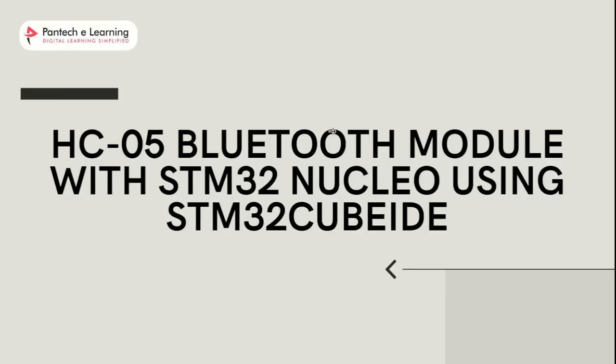So we will use an Android application to communicate with the STM32 Nucleo through this HC-05 Bluetooth module. And also we will see an example of controlling an LED from the Android application using Bluetooth communication. The LED will be connected with an output GPIO pin of the Nucleo, and in effect we will be controlling that particular pin. We are going to use the inbuilt LED.